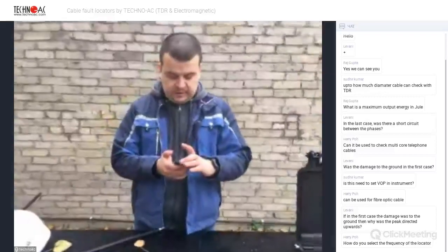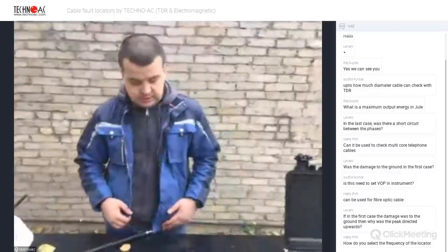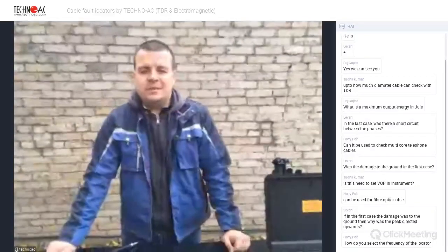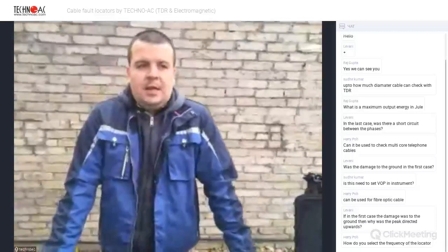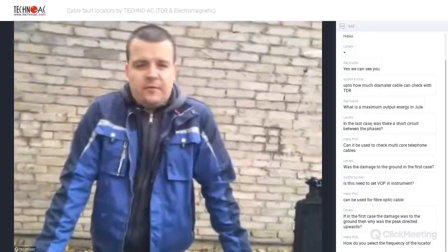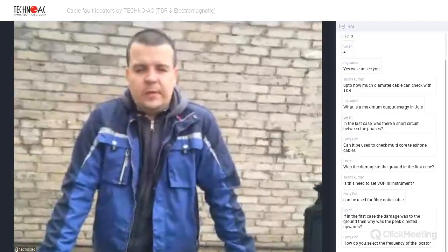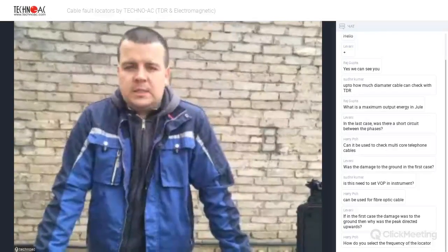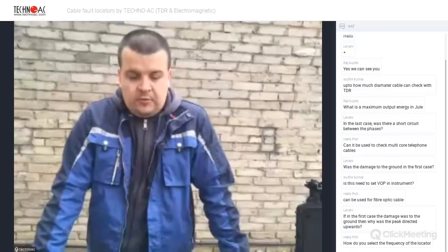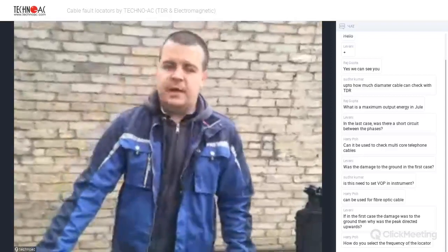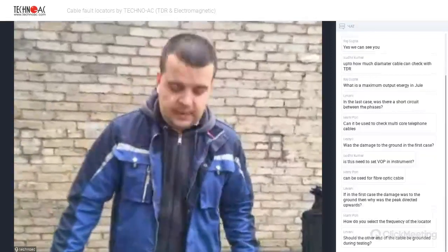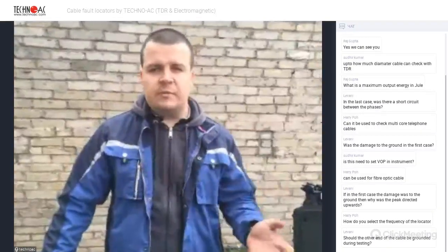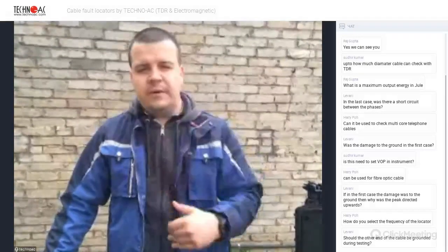How do you select the frequency of the locator? That's a very good question, but it's not connected with the topic of our today's webinar, but I will reply. The general advice for the selection of frequency is the following. Start the usage of transmitter with lowest possible frequency. For different conditions, you have to use different frequencies, and that is fine. But you can't say for sure that these particular conditions require this frequency or these conditions require another frequency.